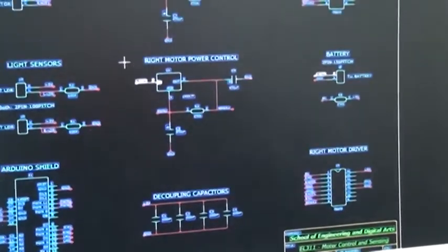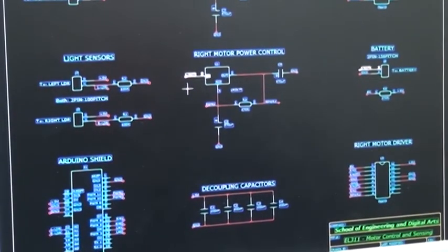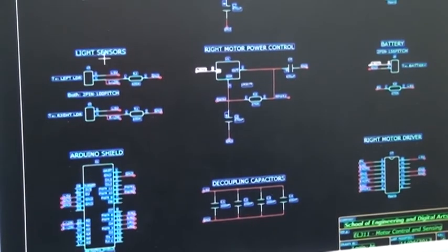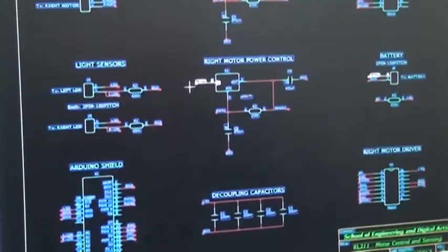So the simplest, most efficient way of drawing circuits is with net names, keeping them isolated so that each section can be described with text, so it says exactly what they are on the tin, and how they're connected together. That's the important thing.